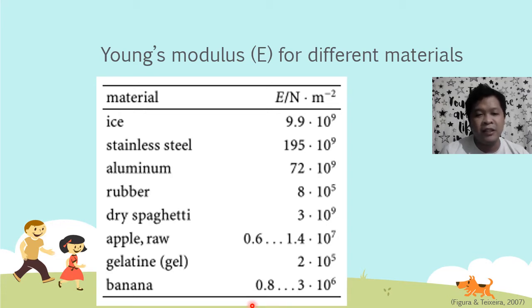Again, how do we interpret the Young's modulus? So isipin natin to, di ba? Stress over strain siya. Okay, slope. So if the value is higher, so mas mataas yung stress dun sa strain, meaning to say you have to apply more stress, and the material would respond by a small amount of strain or deformation.